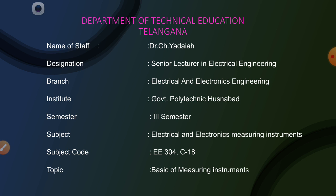The moving iron instruments are further classified into attraction type and repulsion type instruments, and moving coil instruments into permanent magnet and electromagnet instruments. The moving coil instruments are only for DC measurement, whereas the induction type instruments are AC instruments. The remaining can be used for both purposes.